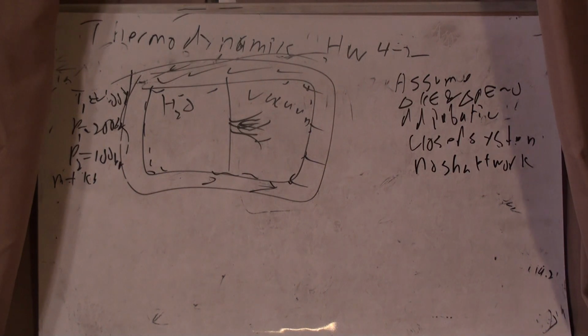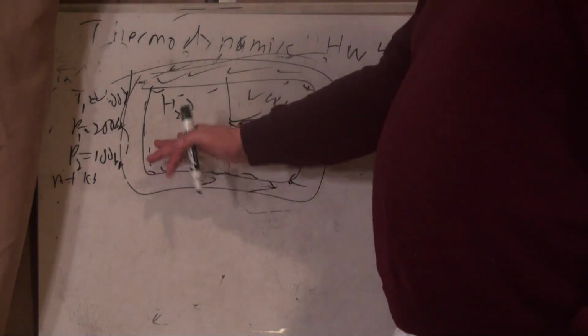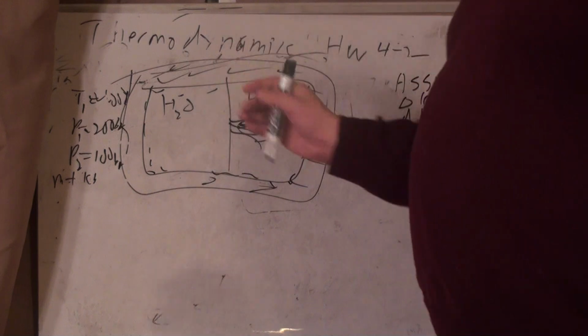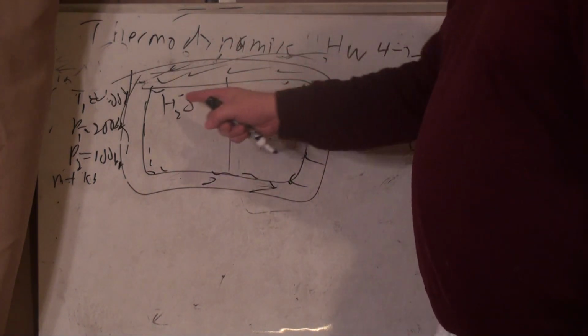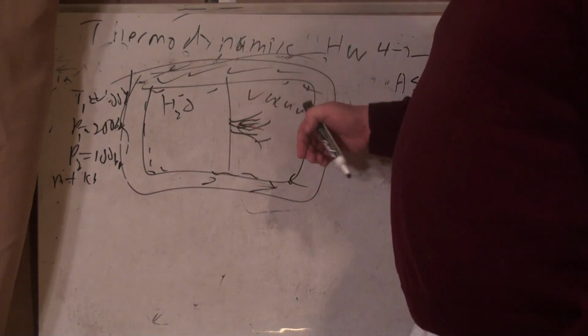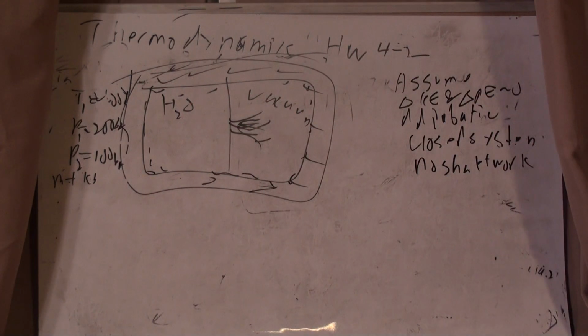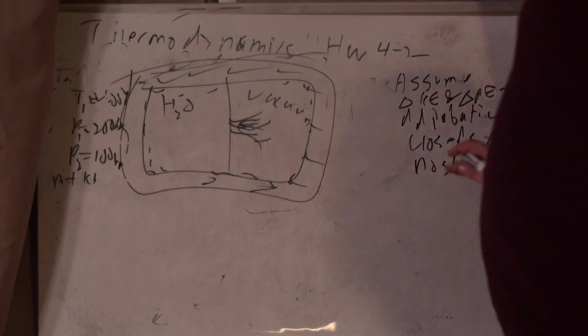The specific volume, well, I guess the specific volume's not going to stay the same, because the water didn't have access to this volume before. And so you have all this volume, and it doesn't change. The boundary does not change shape, and so there isn't any work.